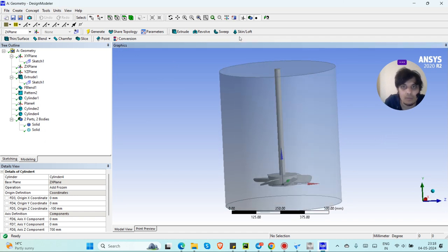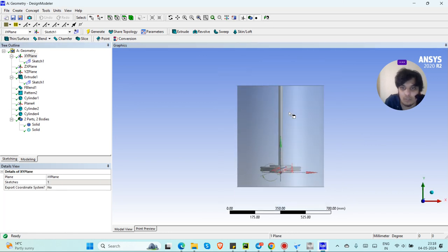Yeah, somewhat. Let's look over it. Yeah, radius 300 mm. Okay, now blend. Select fixed radius, plan, and in the details set it to 100 mm. Activate the edge geometry and select the edge selection filter. Select the two edges bounding the top and the bottom. Control click for multiple selections and apply the selection in the details view and click on generate.